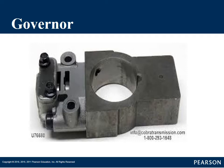Here is a governor. This is off a Ford transmission where we don't have two gears meshing together. This actually slips onto the output shaft of the transmission. There's a pin or a keyway that keeps it locked into place so it doesn't spin on the output shaft, and then a snap ring holds it from sliding off the output shaft. So that whole assembly spins.